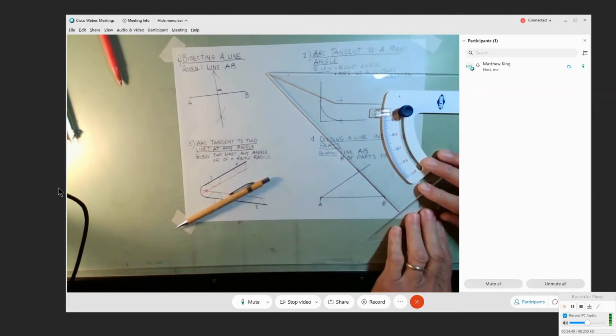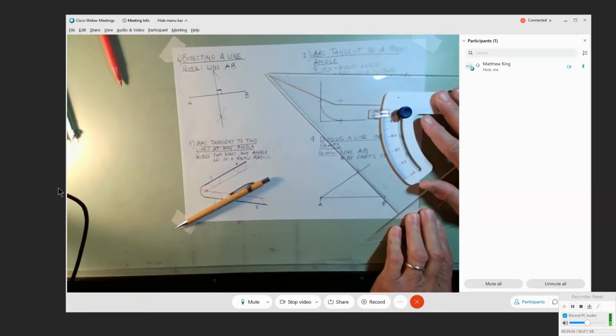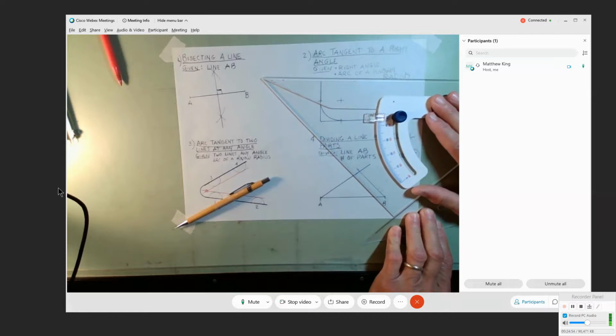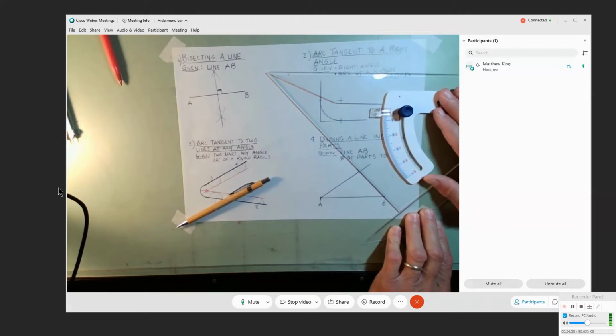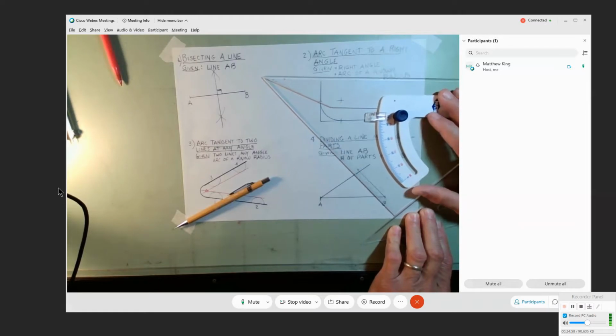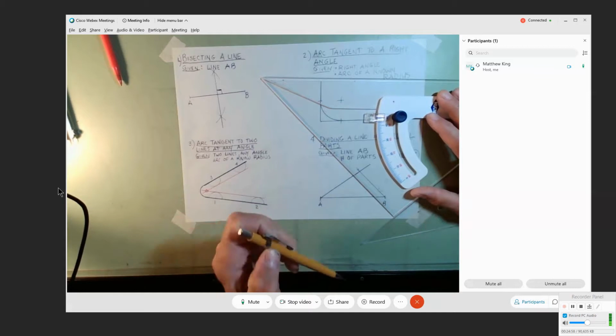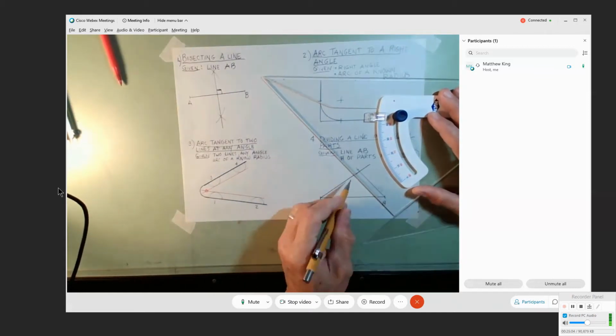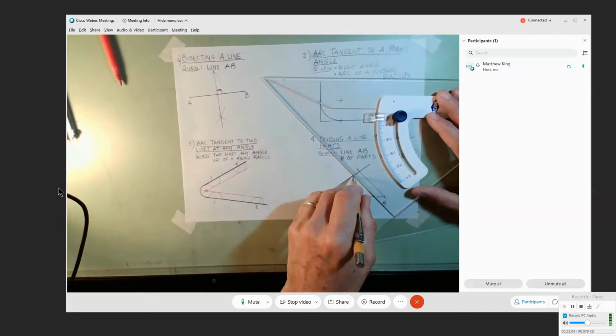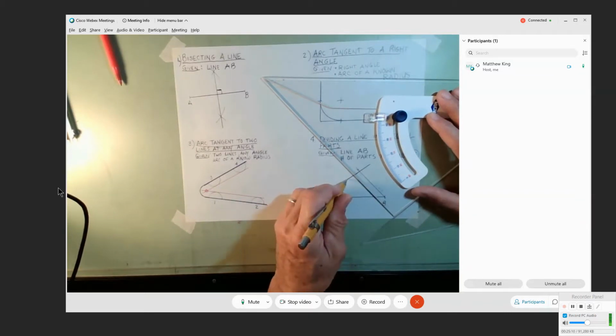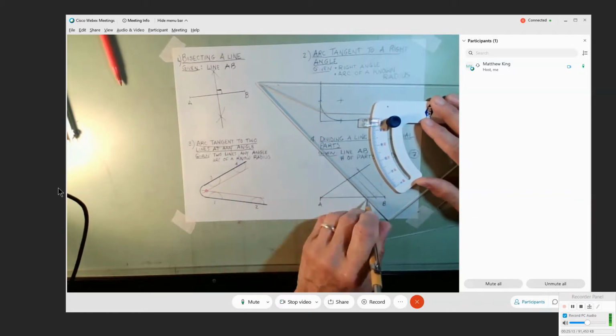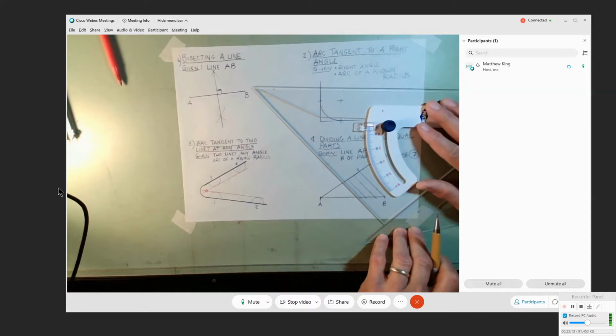And now with this one pressed down and held still, I slide this across to the next one. If you think you messed up, just go back and make sure that this one lines up. But I'm going to slide it over to here, and I'm going to draw another line. And those seem to be in the shadow here, so it's hard to see. And then I'm drawing that down. And I repeat that. Slide this down, draw. Always maintaining this angle.